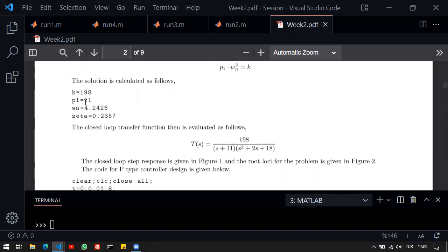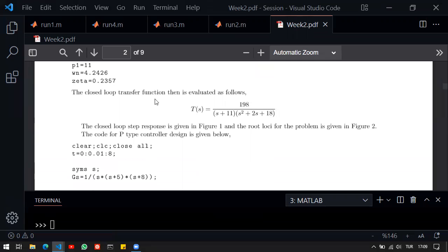Now, for the first case, we had a high k value, a gain value, and also the dominance factor here, which determines if our response or strategy works or not. The ratio there was good, so the distance was sufficient. Therefore, we had a working solution. But the solution had a lower zeta value, which meant that we would have more overshoot.